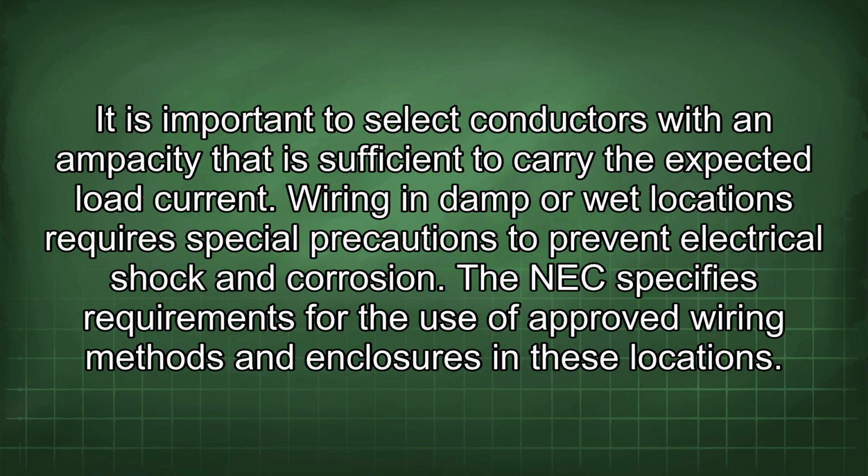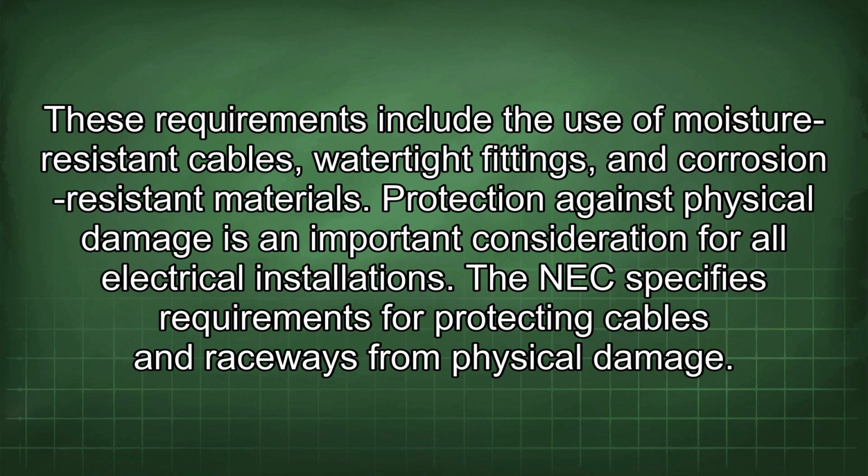Wiring in damp or wet locations requires special precautions to prevent electrical shock and corrosion. The NEC specifies requirements for the use of approved wiring methods and enclosures in these locations. These requirements include the use of moisture-resistant cables, watertight fittings, and corrosion-resistant materials.